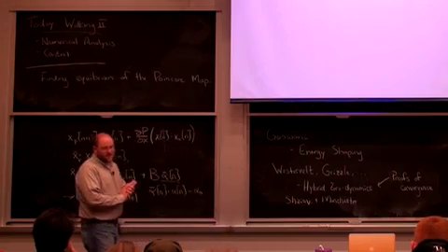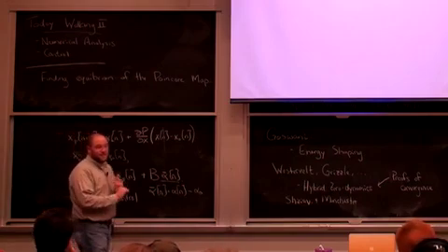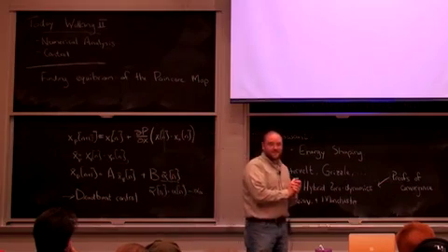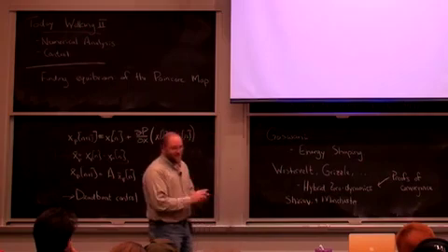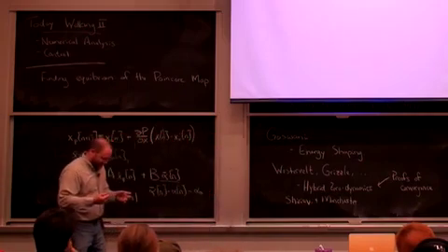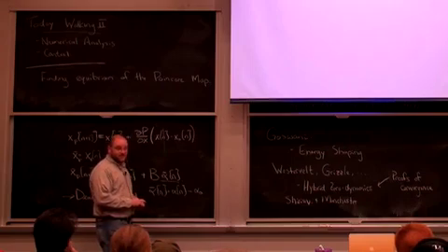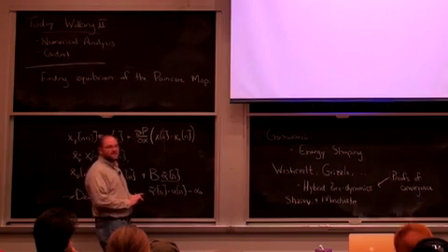But most of the walking robots out there today, most of the successful ones, are all pretty similar to Asimo. And Asimo doesn't do any of this stuff, really. Asimo plays one trick, I could say it sort of in a single line. They try to keep one foot flat on the ground and assume that that foot is bolted to the ground.